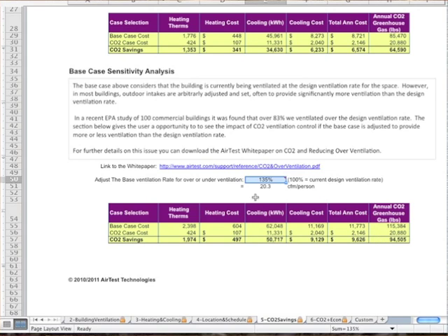And you can see for ventilating, if that initial damper position is 5 CFM per person more open in the space, the savings go from 6,574 to 9,623, almost 1/3 more savings from CO2 if that damper is improperly set.